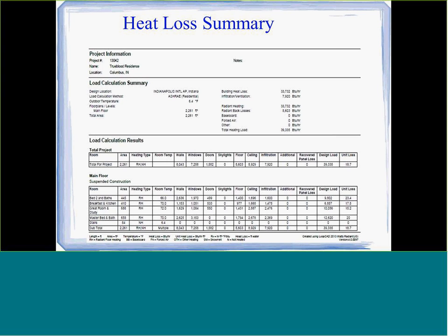That design load is an output of your appliance. So if you've got an 80% heating unit, you may need to upsize it a little more because you still have to have the output, where if you're working with a high efficiency unit where you're 95%, you still have the same output, but your input's going to be less because of the increased efficiency. So you always want to size these on boiler output.